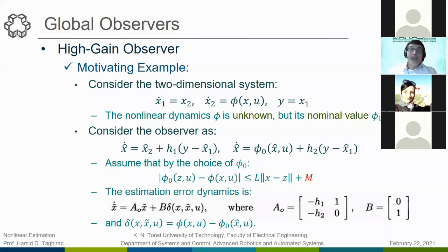And if you add the second, third order, you reduce the conservativeness, but you should do a hell of work to find those parameters. So usually, in the basic and introductory part, as we are talking here, we just go through the Lipschitz condition, and we don't worry about the conservativeness, because what we need is mostly to show that we have convergence to zero.